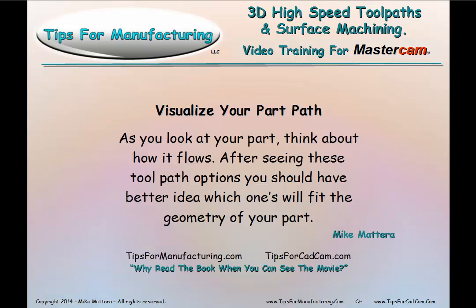So the key is to visualize your toolpath. Look at your part, think about how it flows, and after seeing these toolpath options, you should have a better idea which ones will fit the geometry of your part.